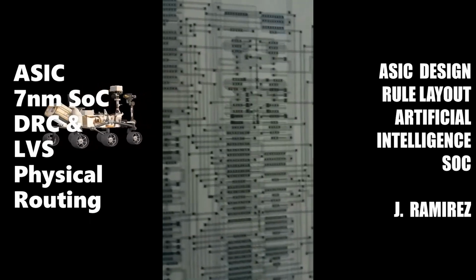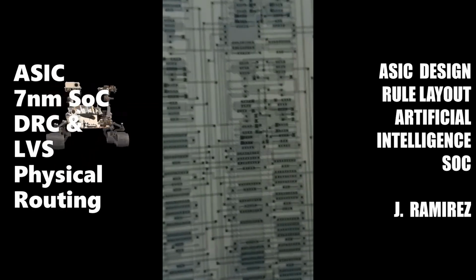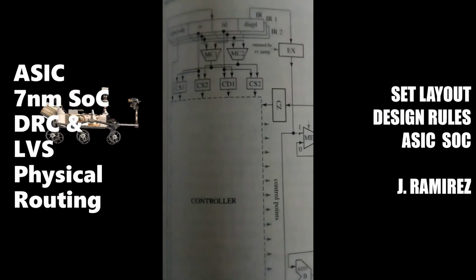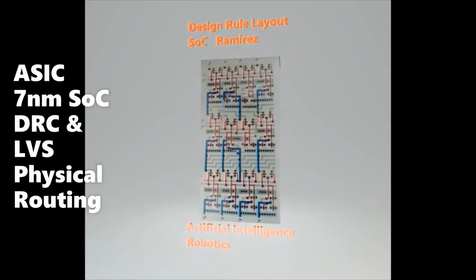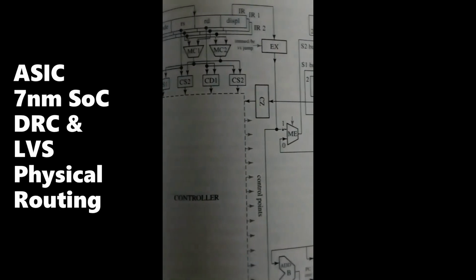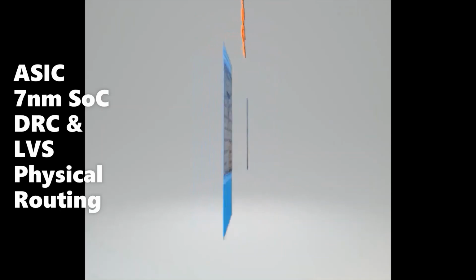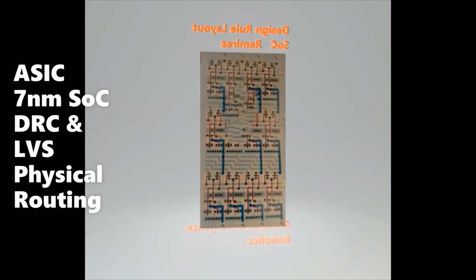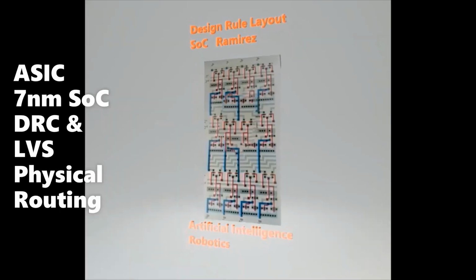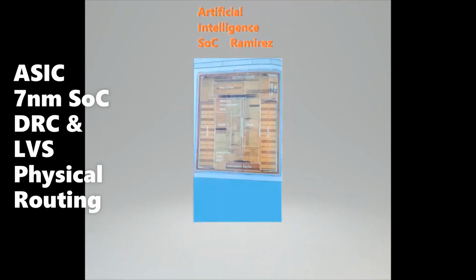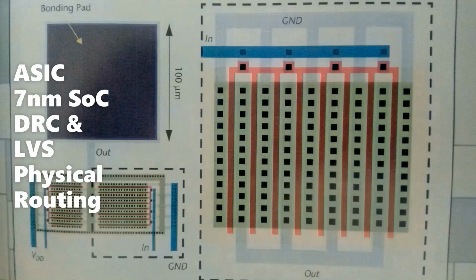Two main approaches to global routing are one net at a time or all nets at once. With the inclusion of timing-driven routing objectives, the routing problem becomes much harder and requires understanding the differences between finding the shortest net and finding the net with the shortest delay. Different types of detail routing include channel routing and area-based or maze routing.